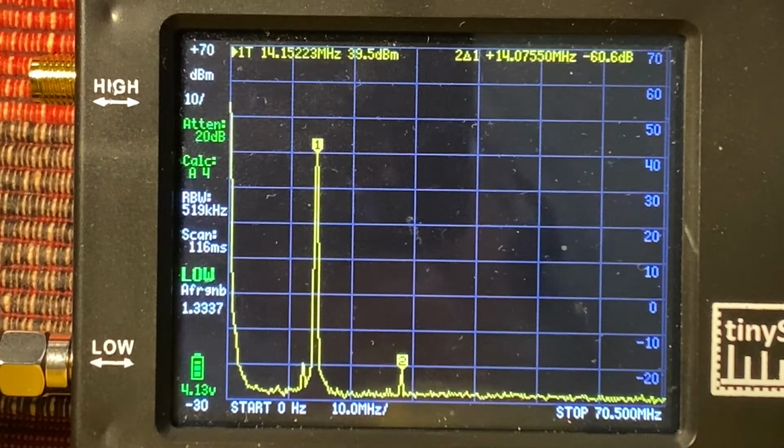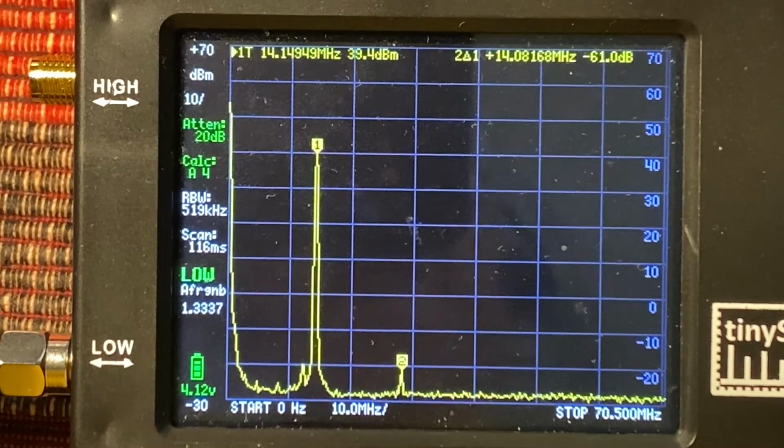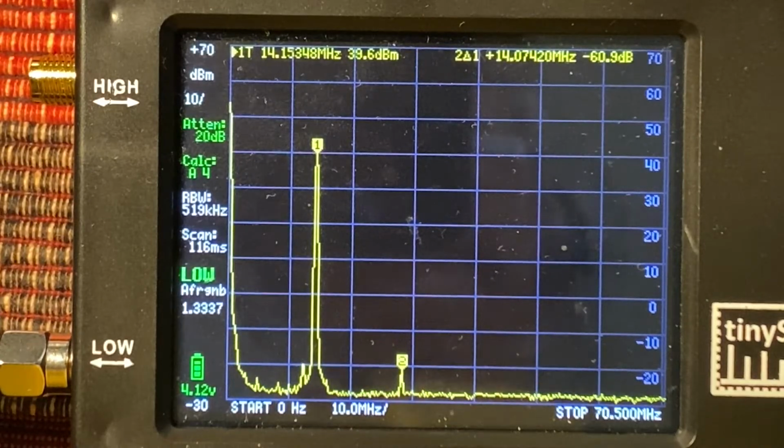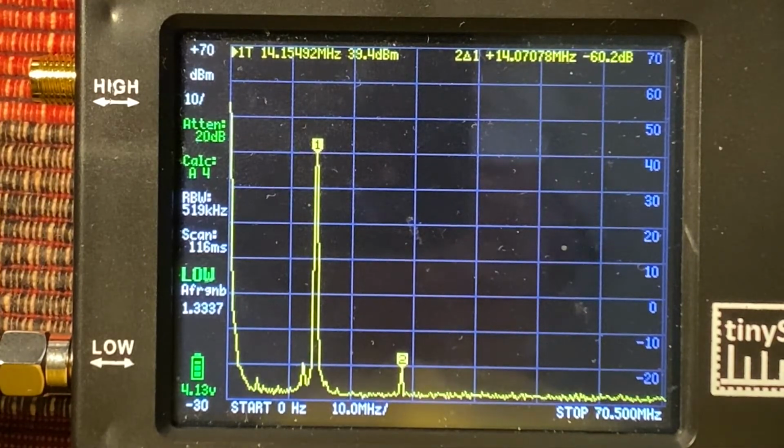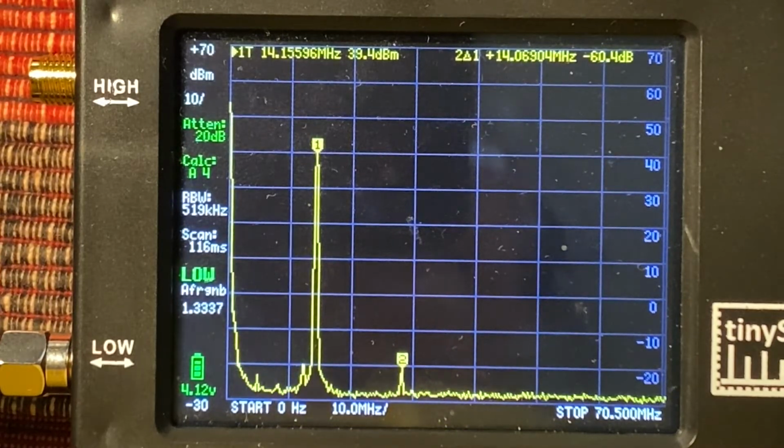The results are very comparable to the ones from the oscilloscope, although the oscilloscope has a somewhat wider dynamic range. And as a result, it shows some other spurious signals that we may or may not care to know are there. However, both devices have more than adequate range to ensure legal compliance with the amateur radio laws in most countries at these frequencies. At other frequencies, different harmonic regulations apply.